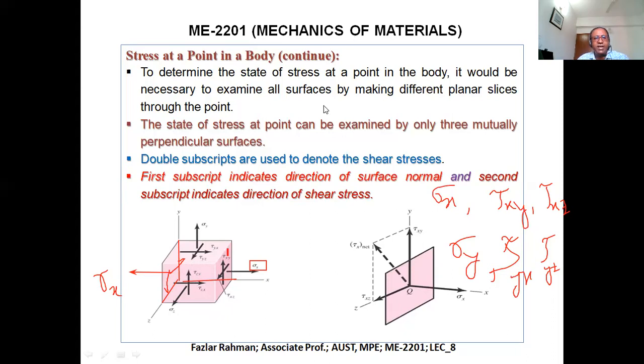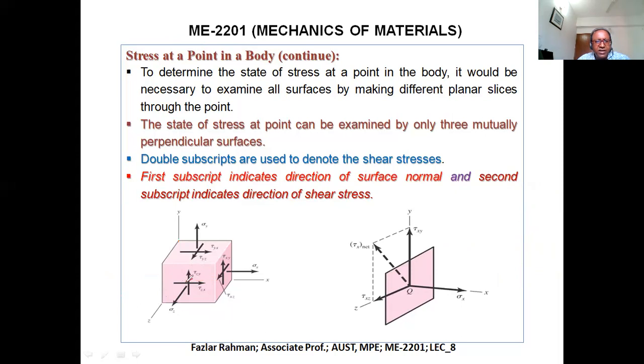So how did you see? These are showing 3 faces, this face, this face, this face. Actually, it has 6 faces. Some force works over here, also in the bottom, also on the back side, but they are equal and opposite. So always, in total how many stresses over here? 9 stresses. These 9 stresses always work inside every point of the body.